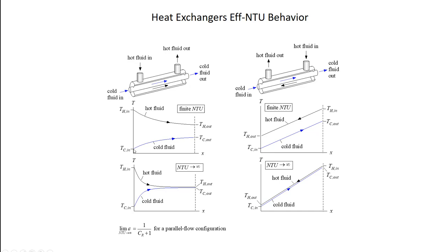Well, for one thing, I know that however much the cold temperature rises, that's how much the hot temperature should drop. So that's shown. The other thing I know is that the cold temperature rise and the hot temperature drop should be pretty substantial, right? So that's also reflected here. If I go over here and do the same thing for the counterflow heat exchanger, I'm sorry, this is a parallel flow heat exchanger. Let's go for the counterflow heat exchanger.